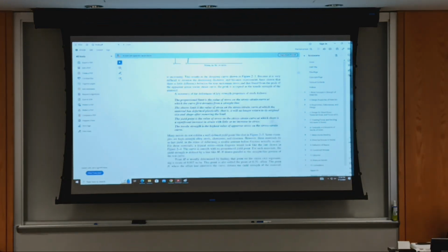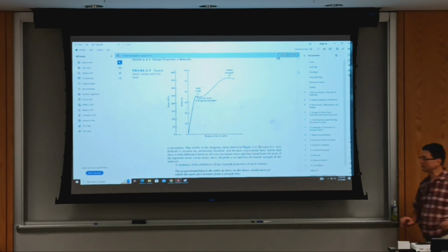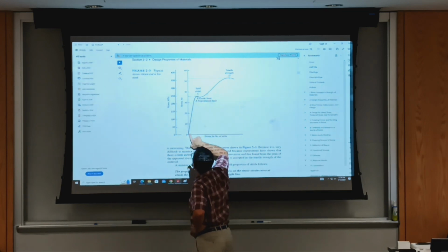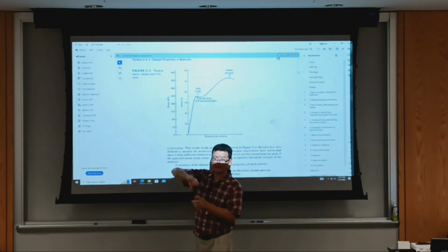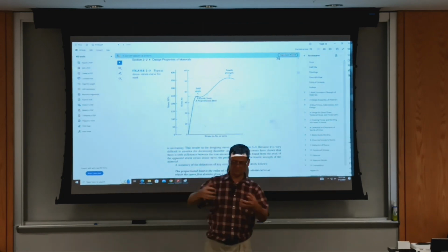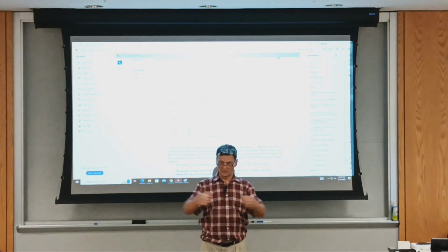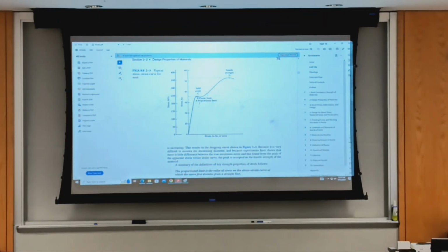We discussed stress and strain, where the proportional limit is where there's a linear relationship between the stress and strain. So this would be essentially, although it was very minute deformation, where the specimen behaves like an elastic spring, but a very stiff spring. Like a rubber band. Well, that's not linear, but if it was a coil spring, you can see they are really hard to stretch, at least by hand. Anyway, this is where we can assume a tensile specimen behaves like a spring.